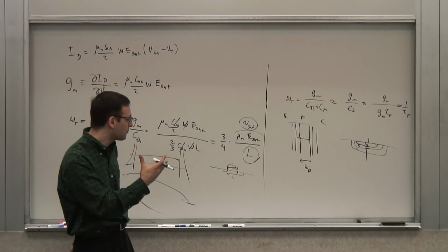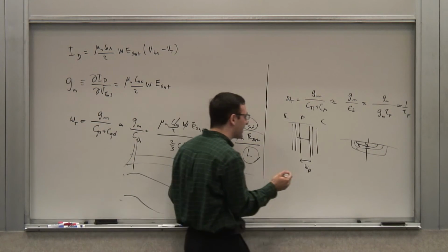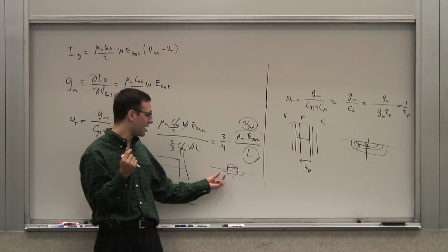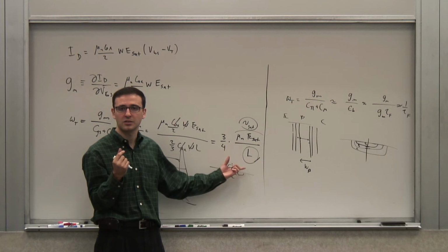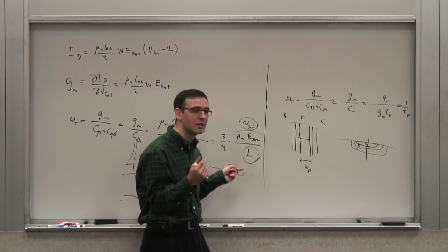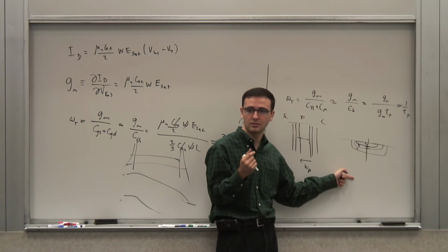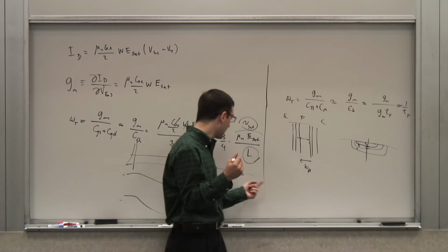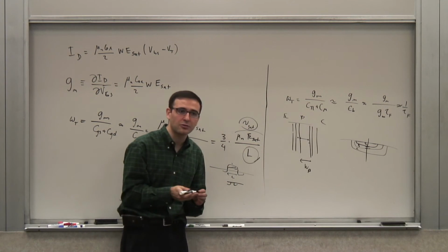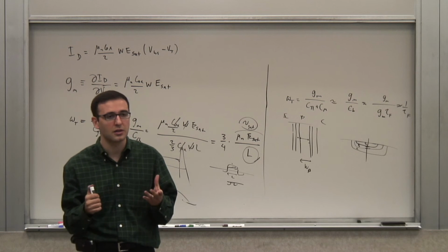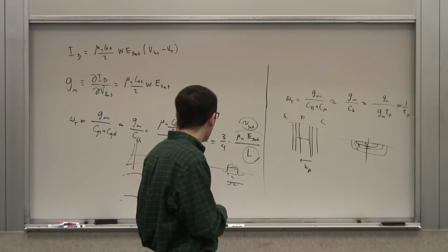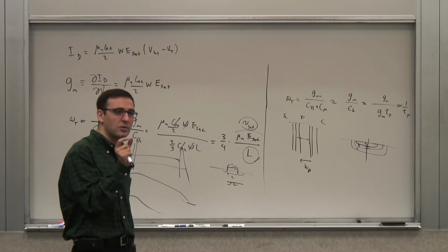So for a given process technology, typically the way it has been is that you can actually get a thinner base than your channel length by this control, because you have more control of that vertical parameter than the lateral parameter. That also works in favor of the bipolar transistor. But nowadays, these guys are catching up, right? Because you are trying to make this as small as you can. It's done through lithography, and it's an optical process, right?